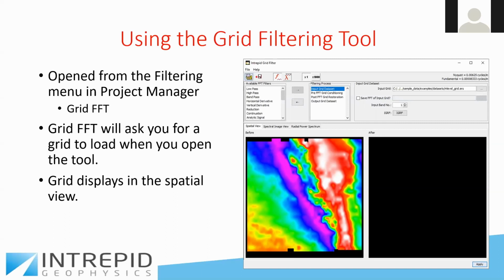So using the grid filtering tool, it's opened from the filtering menu in the project manager, and it's the grid FFT option. When you open it, it will prompt you for a grid to load. And the grid displays in the spatial view in the grid filter window.